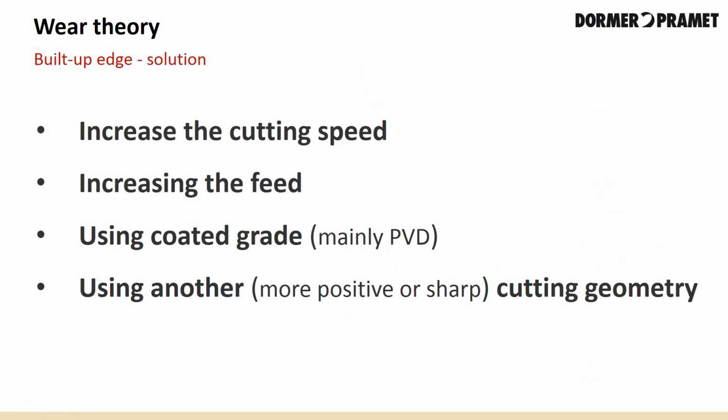So how do we reduce the built-up edge? We can increase the cutting speed, increase the feed. We can also use a coated grade or a PVD coating, or use another more positive or sharp cutting geometry.